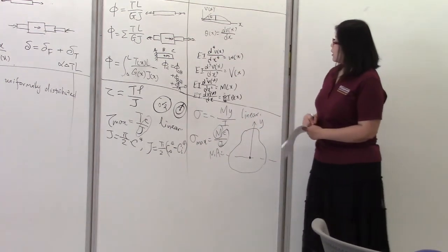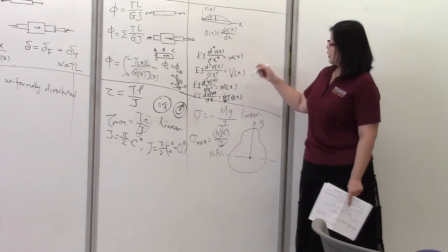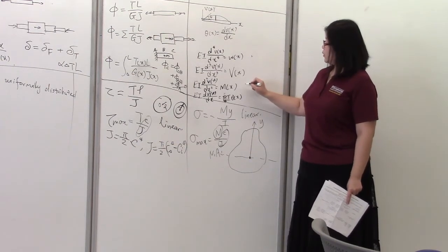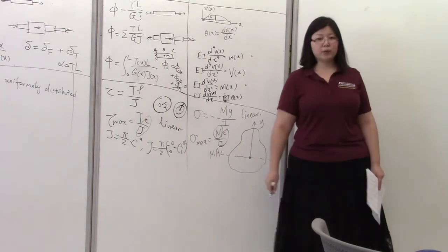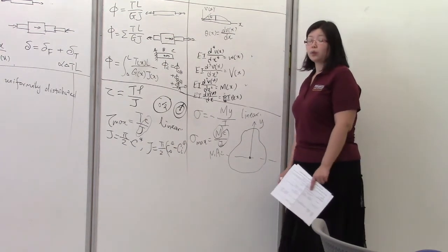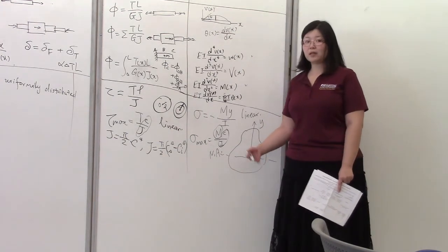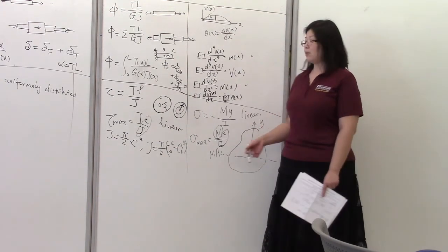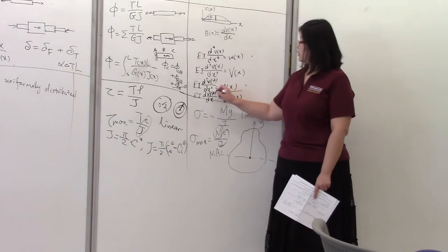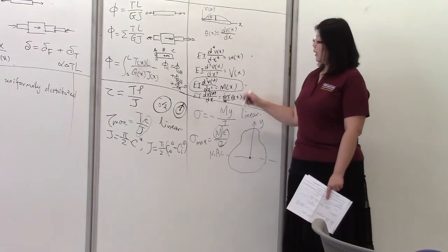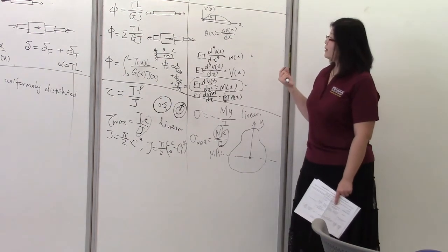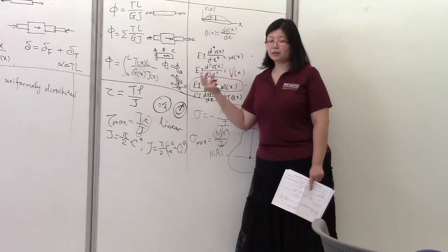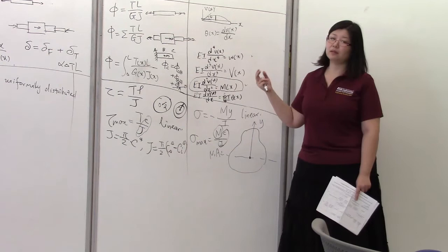Alright, so again, in general we either start with the 4th order differential equation or the 2nd order differential equation. We use the 4th order differential equation when the distributed load is quite complicated, like a sine function, a quadratic function, etc. Otherwise, we always start with the 2nd order differential equation. And we apply this to different segments of the beam. And the way the beam is divided into segments has been discussed earlier.